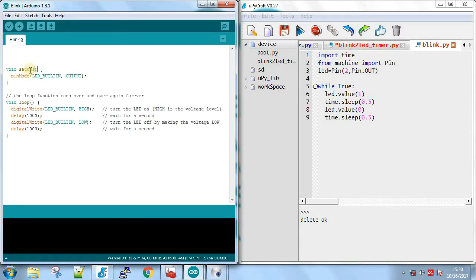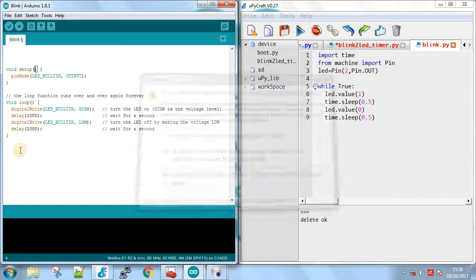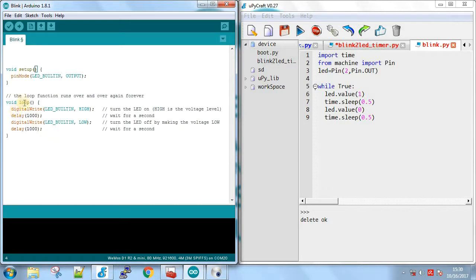So as you can see, the setup is mainly used for setting up things, which pin you want to use, and Wi-Fi initialization and Wi-Fi settings, if you want to use Wi-Fi on the Wemos D1 Mini, etc. And the second function, loop, is your main application, which is what we want to do with those pins, what we want to do if something happens with one of those pins. So we put it in here, and this code runs forever until you change the code again later.